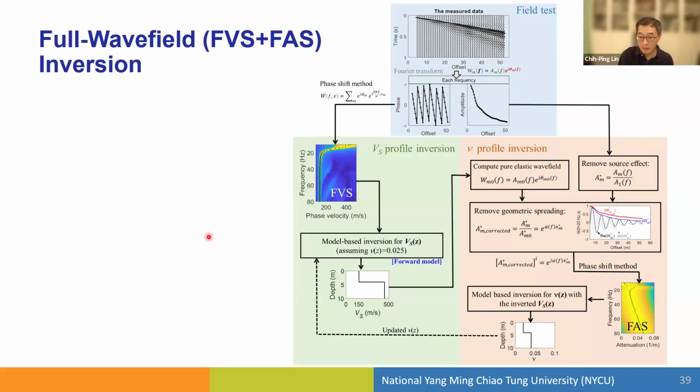The air wave and the surface wave, leaky mode, can be added together, but after wave field transformation, you can see the air wave and the surface wave separately. So this can also be modeled quite nicely. We are now developing a microphone system and trying to come up with a full wave field inversion inspection tool, an efficient tool for pavement inspection.